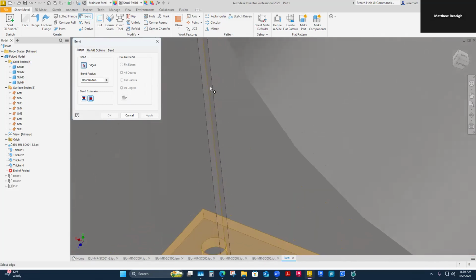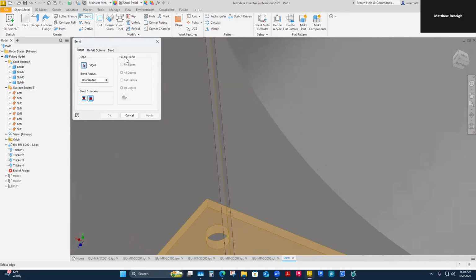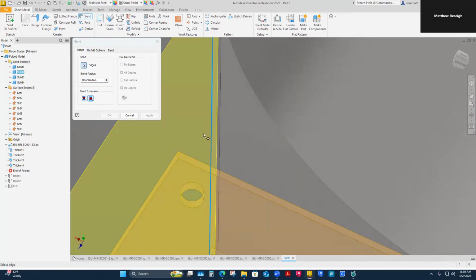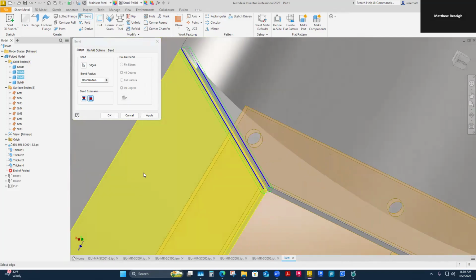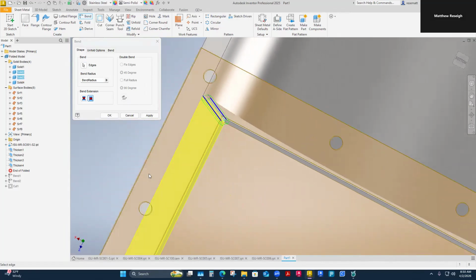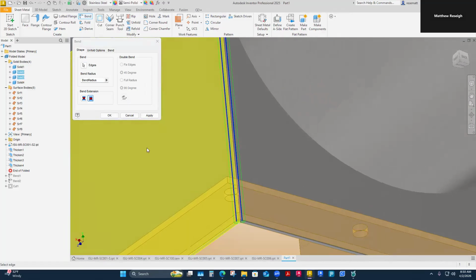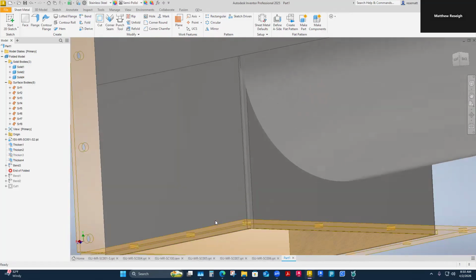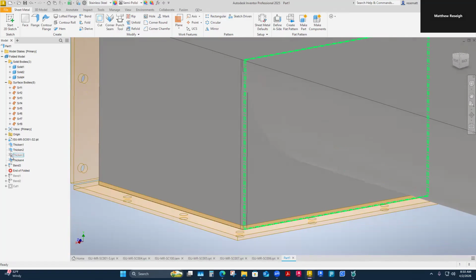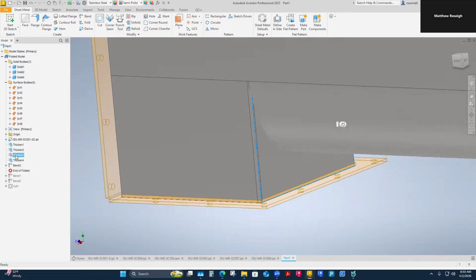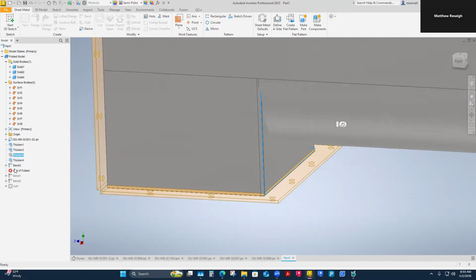And so it recognizes this is a double bend, a double edge bend. So it needs two edges to make this bend now. And essentially, it looks like back to what we were doing with the original part. I'm going to say okay on this. It's just two edge selections and okay. And what it does is, this shows that this was a thicken command, but now it's kind of inactive. It's because it's been consumed, and the program's smart enough to know I've just joined two solids. And if I'm bending those, they're going to be one piece. So it is still an important step that it was here, but it's been overridden by my bend command now.